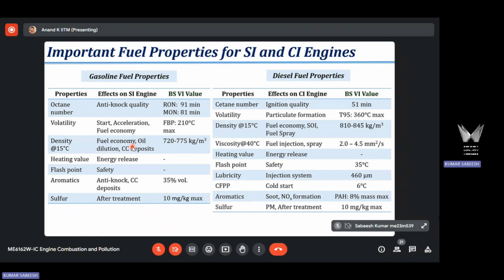Yeah. So you need to use additives definitely. And as I said, in Western countries, you need to use some starting aid also. You need to have an intake heating system. And there are additives like cold flow improver additive, because fluidity, I'm going to talk about that in diesel properties, is defined by this CFPP. The fluidity of the fuel gets affected based on the surrounding ambient temperature.